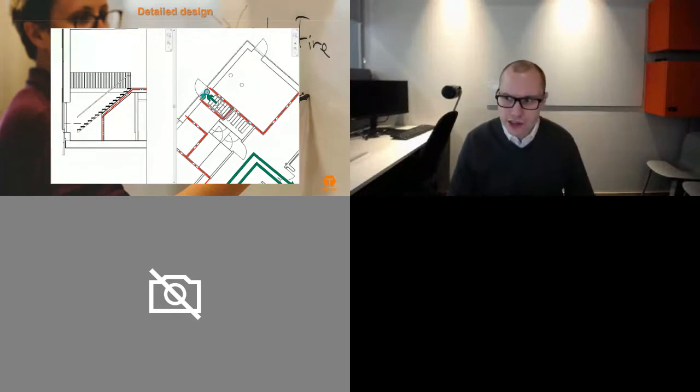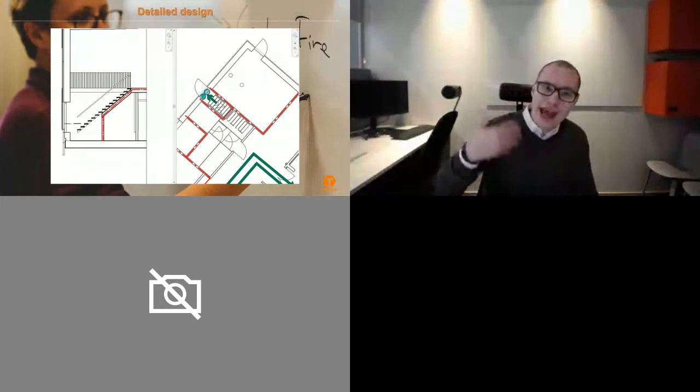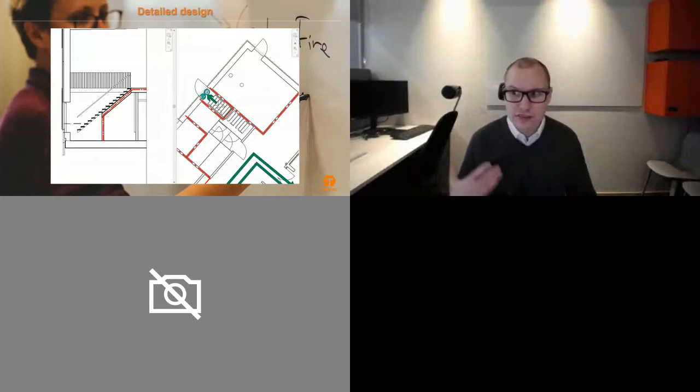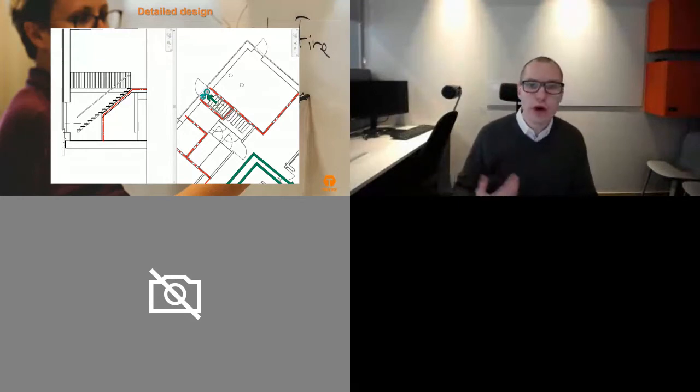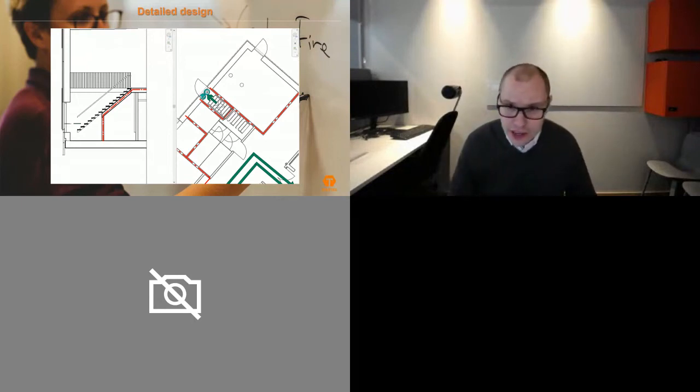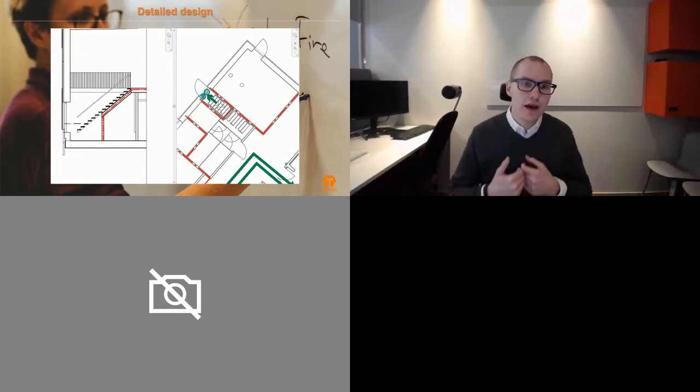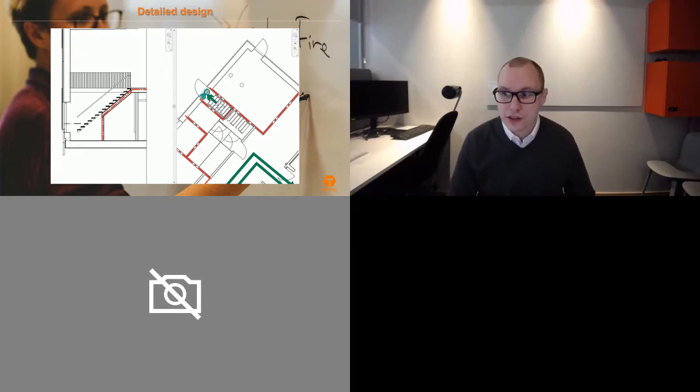But having a fire safety engineer creating their own model, we can actually start to add more drawings explaining what we mean with the requirements that we have. So this is a traditional staircase, and we want to have a fire resistance under the staircase. And it's quite hard, as most people understand, to showcase this in a floor plan. So just by being able now to do sections and explain that under this staircase there should be a fire resistance, because there is a fire compartmentation under the stairs.